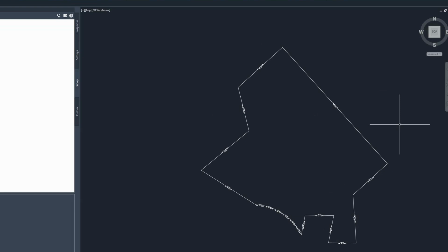Once you do, that's when you say, hey, I found the monumentation, that's great, let me do my control network, let me run that traverse, that setup, and then shoot in all these points with the total station for higher accuracy measurements. That's something that you'll eventually do in future courses, so try to remember what you're doing here, and this is really the starting point. This is the push-off point for a boundary survey.